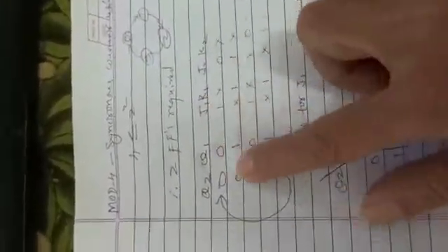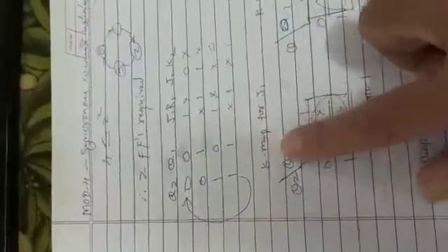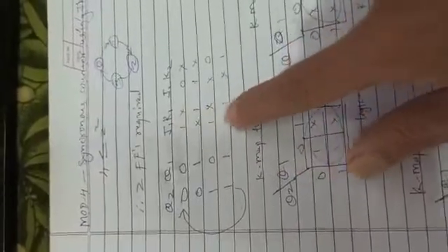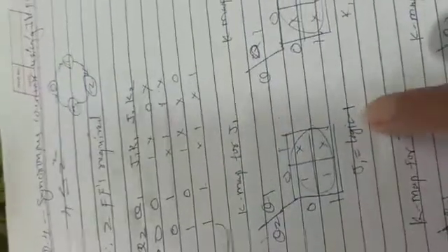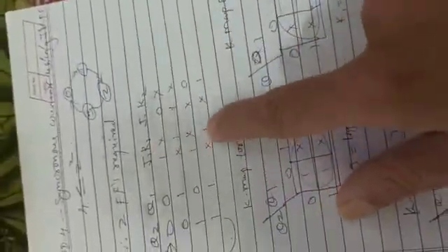Okay, now in a synchronous counter we design a circuit for giving the inputs, and the output of the counter we use as an input. Then the K-map for J1. So these values we have to enter in a K-map. Here it is just a two variable K-map, Q2 and Q1, and these values are entered because this is the K-map for J1. So you can combine all 4 cells, so J1 will be logic 1. Similarly, these values you can enter in a K-map for K1. So here also 4 cells can be combined and K1 will be logic 1.